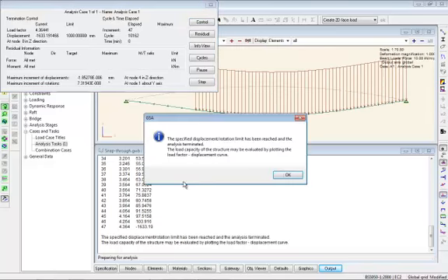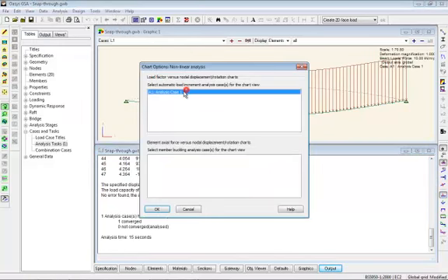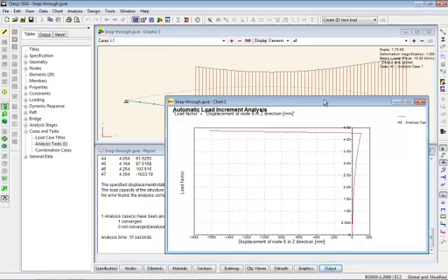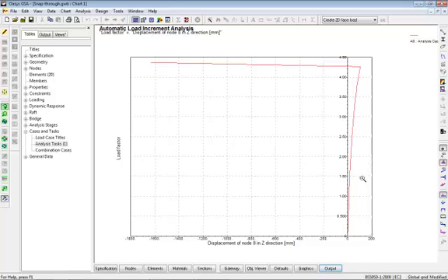Right. Okay. View the graph. That's better. You see the graph, deflection in the middle point, and you can see where the deflection has snapped through, it snaps through at a value of about 4.3 times the applied load. So you could view it as a factor of safety of 4.3 for that particular asymmetric load case. Obviously you need to run a few.